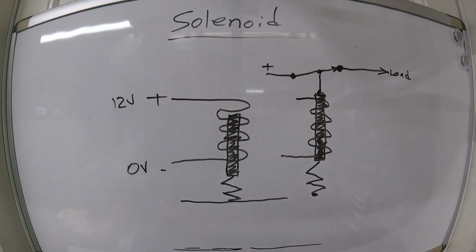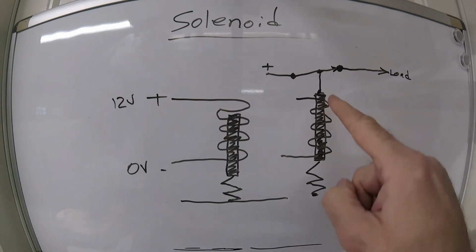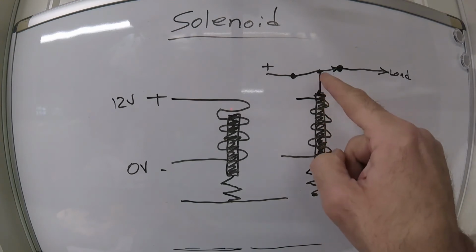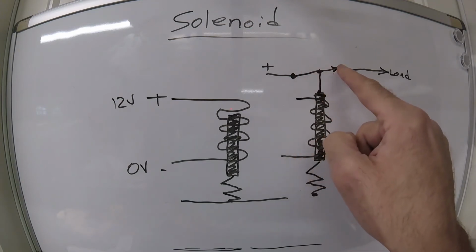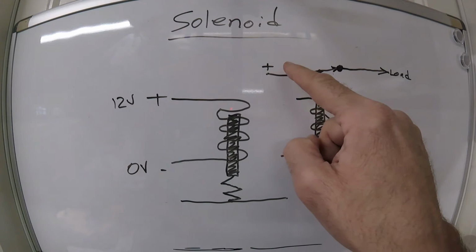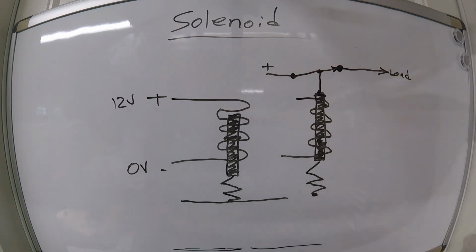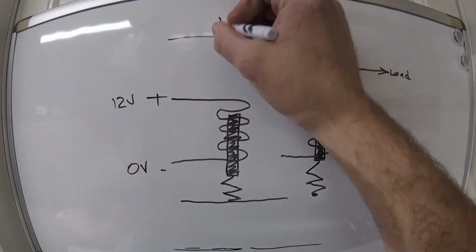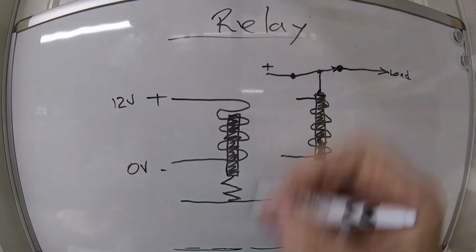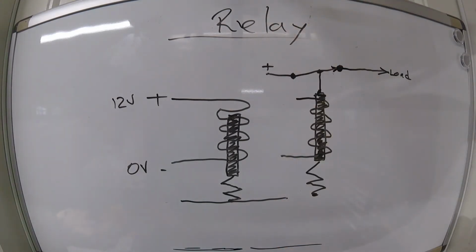in our circuit. Well, if we do that, and we use this moving iron bar to move that switch and make it close, then we can transfer electricity through our circuit. And when we do that, we have taken a solenoid and we have created a relay. And that's why solenoids are important. We use them for other things in machines and vehicles, but for what we're going to be talking about in these lessons, the relay is the more important thing.